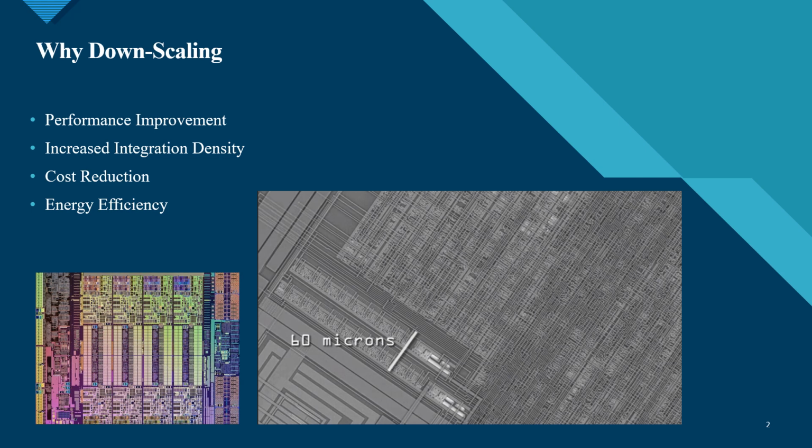There are both technological and economic advantages in reducing the dimensions of transistors and cramming more and more into a chip. The first one is performance improvement. Smaller MOSFETs typically exhibit faster switching speeds and lower power consumption compared to their larger counterparts. This is due to reduced parasitic capacitances and resistances, leading to improved performance in electronic devices such as computers, smartphones, tablets, etc.